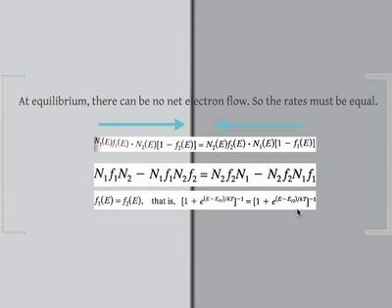Because remember, the Fermi level typically depends on temperature, depends on band gap and all that stuff, right? Okay. It depends on doping. Remember we talked about the Fermi level goes closer to the conduction band, it's n-type, goes closer to the valence band, it's p-type. Well, but what it's saying here is that if you take two materials, n-type and p-type, and put them together, the Fermi levels have to match.